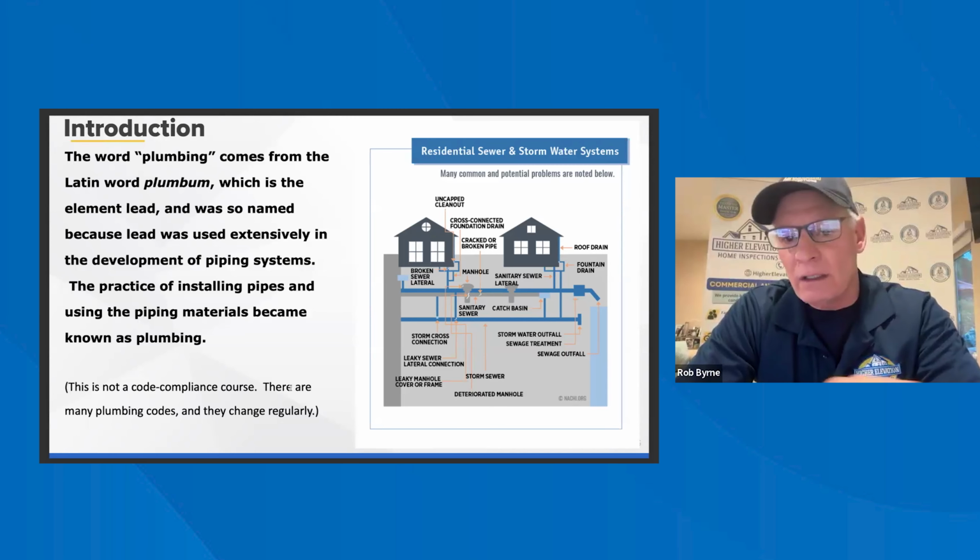The standards tell us to start with the installation of hot and cold water faucets, active plumbing leaks, and toilets that were damaged, loose, or leaking, or had tank components that didn't operate. So we're going to start 3.6, the plumbing portion of the inspection. The standards tell us to start the inspection at the main water shutoff. We are required, if accessible, to state what the main line is and where the shutoff is.